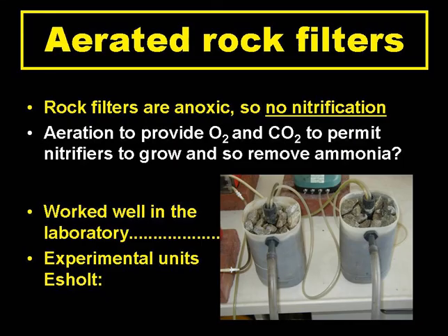Rock filters soon become anoxic, so there's no removal of ammonia by nitrification. Here at Leeds, we wondered, if we aerated the rock filter, would we get nitrification? A final year undergraduate student here in Leeds did his project work on this a few years ago, and he found that aerated rock filters worked very well at lab scale.